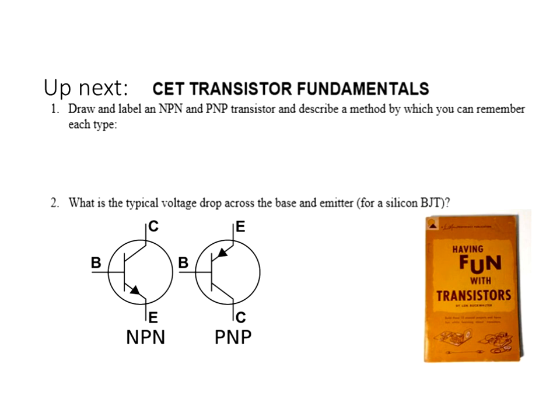It's not to amplify or switch. I get that answer so common. Here's how it works. First of all, there's 3 terminals. 2 terminals that carry all of the current, and 1 terminal that is used as a controlling terminal. And so, the collector and the emitter, there's always two terminals where most of the big current flows. And I use a tiny, tiny current here on the base to control this over here. That's how a transistor works. I hope you got that.